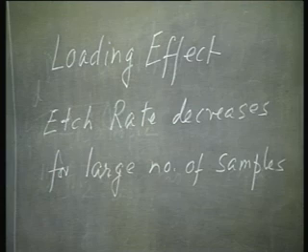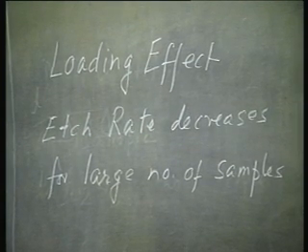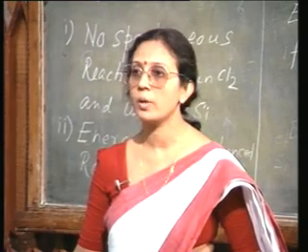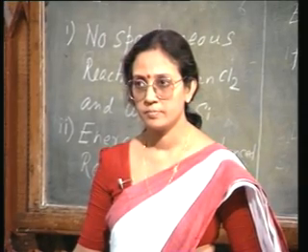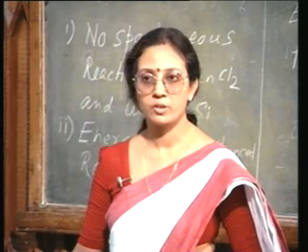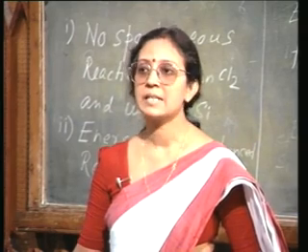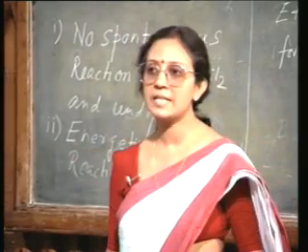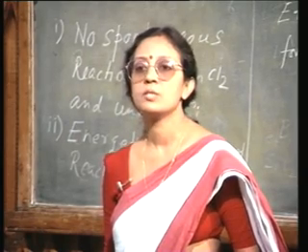Particularly when you have spontaneous vigorous chemical reaction like fluorine based etching of silicon, this loading effect is quite a dominating factor. Okay? So, how to minimize the loading effect? Obviously, for mass production we would like to minimize the loading effect, and this can be minimized simply by keeping the reactor area much larger compared to your total sample area.